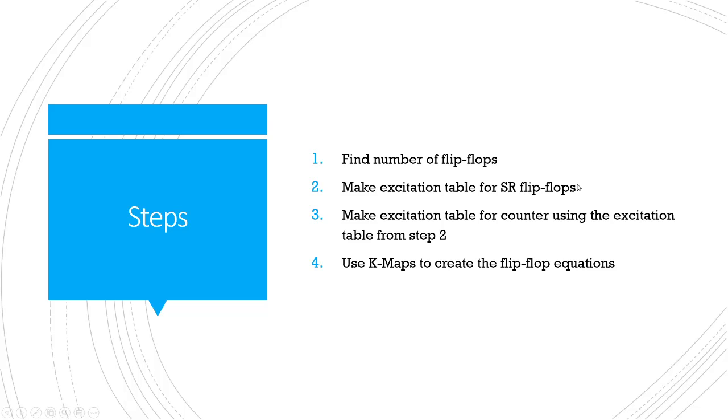Now our methodology to approach this problem will be to find the number of flip-flops we need, make our SR flip-flop table. We will use that SR flip-flop table to make our excitation table for our counter, and then finally we will get our flip-flop equations from our K-maps.